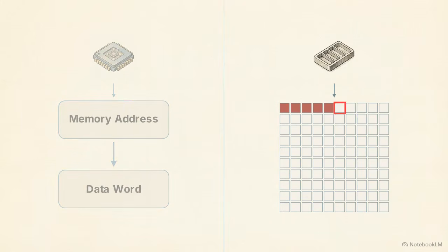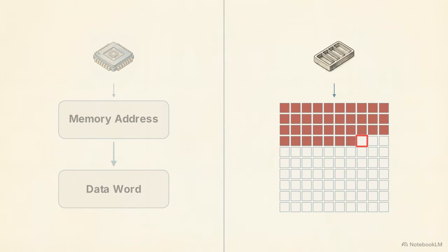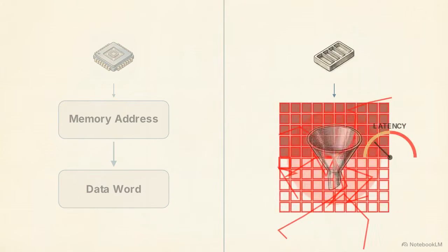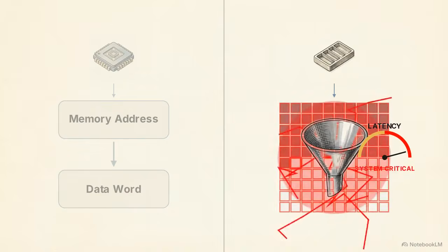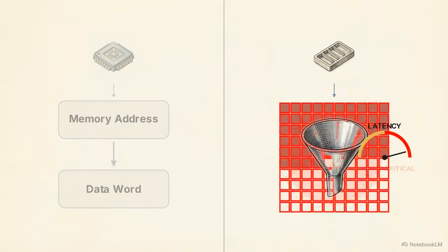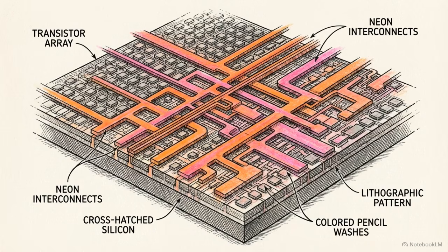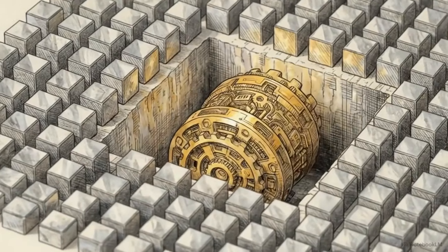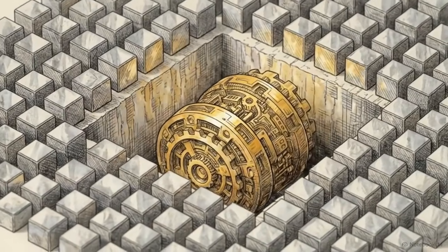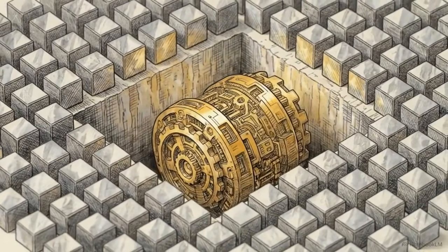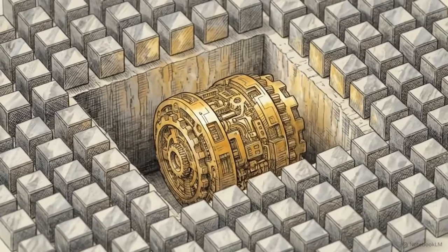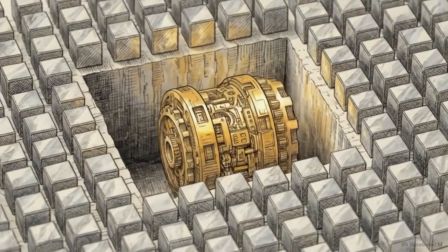The processor supplies a specific data word and must instantly find its stored physical address. Forcing a standard array to execute this search sequentially creates extreme latency and an immediate system bottleneck. Solving for high-bandwidth parallel access or instant data search requires physically altering the topology of the foundational memory transistor cell itself. Achieving modern compute speeds requires abandoning standard, dense memory structures. Engineers sacrifice physical silicon space to embed specialized logic directly into the storage layer.